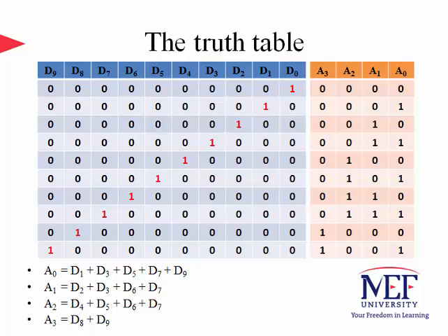One thing you would notice is that not all the input combinations are covered, and thus if the input bit string contains more than one 1, the encoder will not work. A good design should compensate for all possible input combinations.